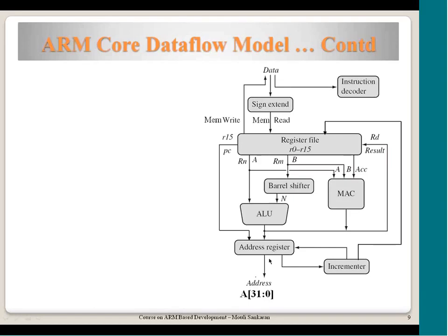It can perform only instruction access provided there is no memory access in the instruction. But suppose we have a sequence of instructions which are all arithmetic instructions like add or subtract, or any operation which is internally done with the register content, and there is no need for accessing any memory. Then the processor can keep on sending the PC value to access the instructions, and keep on incrementing it. If there is no jump or branch to some other address, then it can sequentially access the instructions in the memory, and keep on processing them inside.